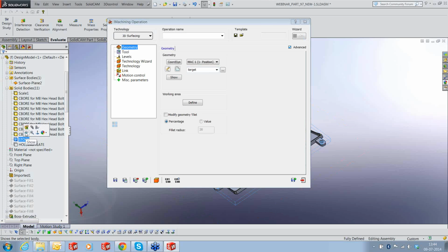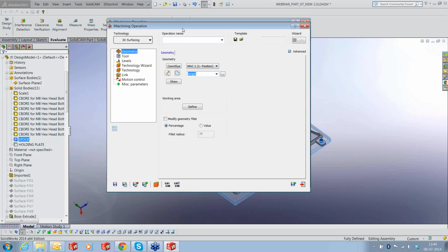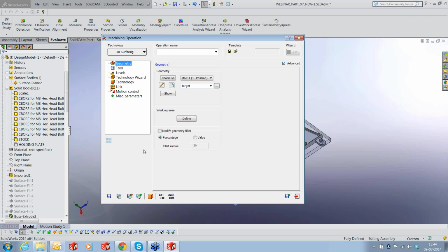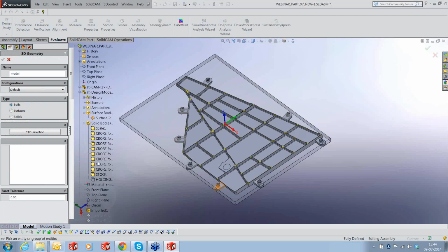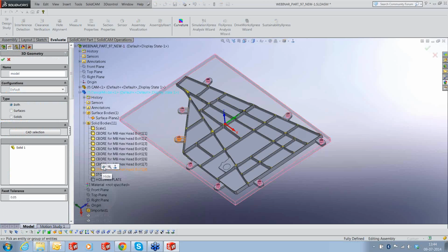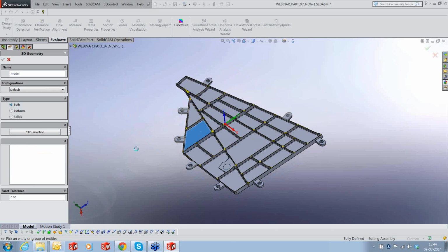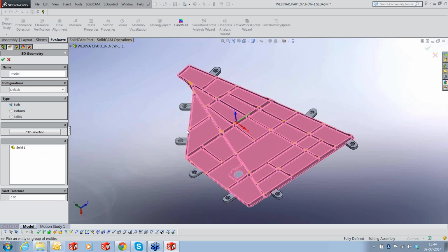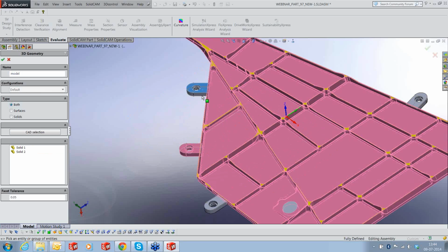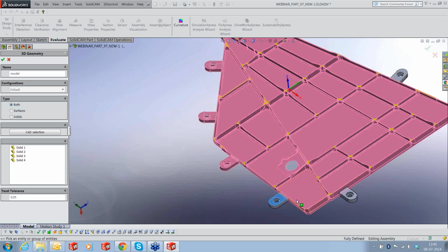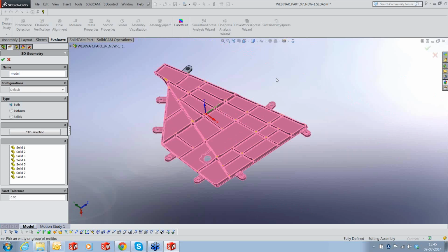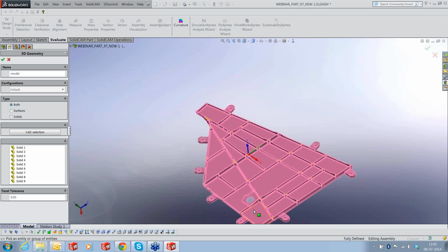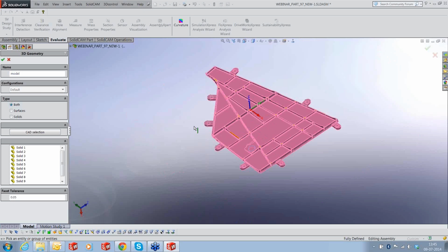We will just switch on the stock because I will be needing the contours. Okay, and I'm not going to use target up here. I'll say new, and okay, moment, let me switch off the stock. I'm going to have to select the main part and the lugs. We are creating a local target inside this particular operation, which will only be used for this operation. So I don't have to really change my original target that was defined, and also this surface. So wherever I need all of them together, I can select this model. Okay.